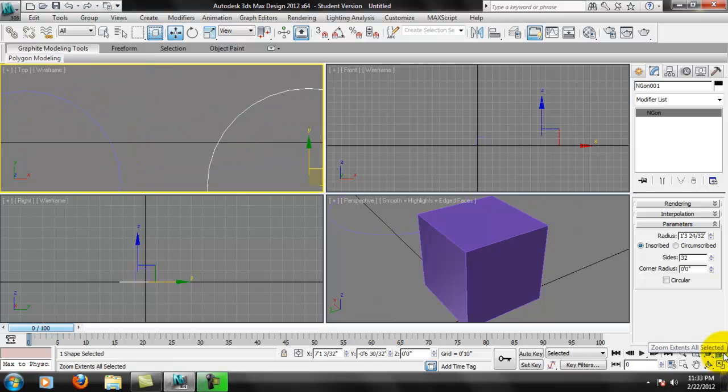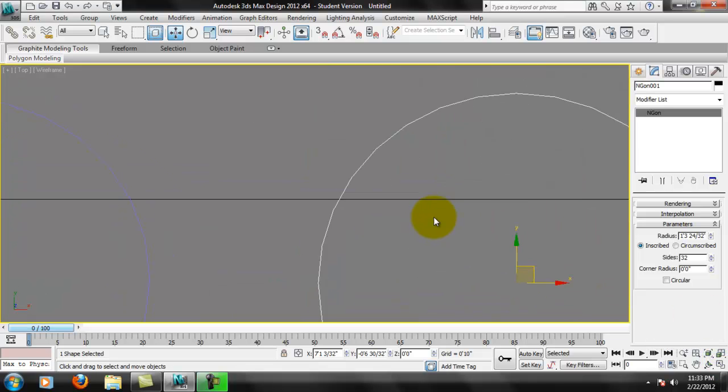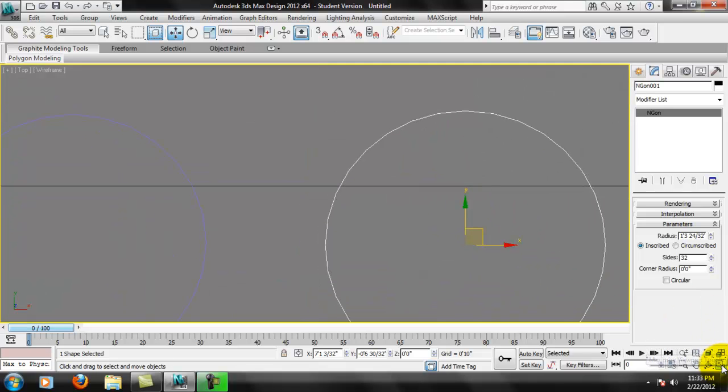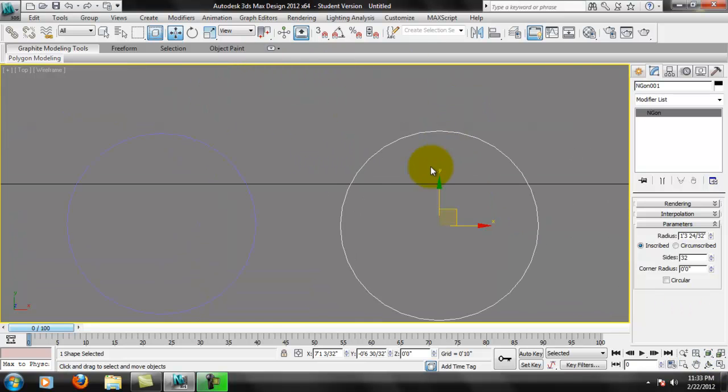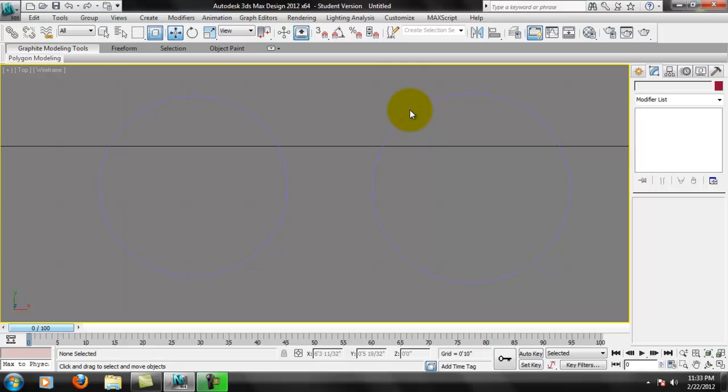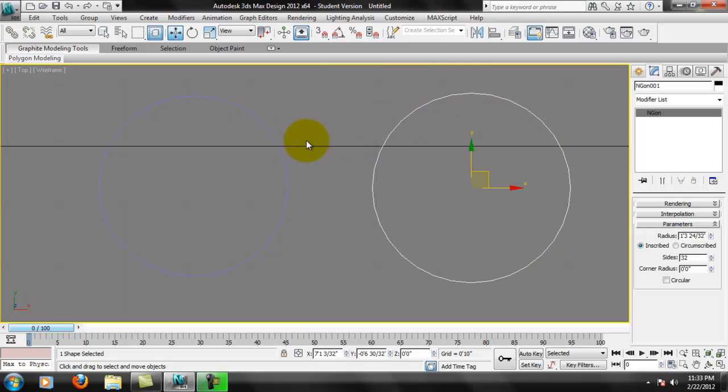make this bigger since we have that luxury. Remember I did that by hitting down here the maximize viewport, so that will switch whatever viewport's active to the full screen. So I have essentially created the 2 identical things, and sometimes if you're into CNC programming or anything like that, sometimes G-code might mess up if you create a circle, like say in Mastercam. So sometimes the only way out of that is to actually create a polygon with a lot of sides.